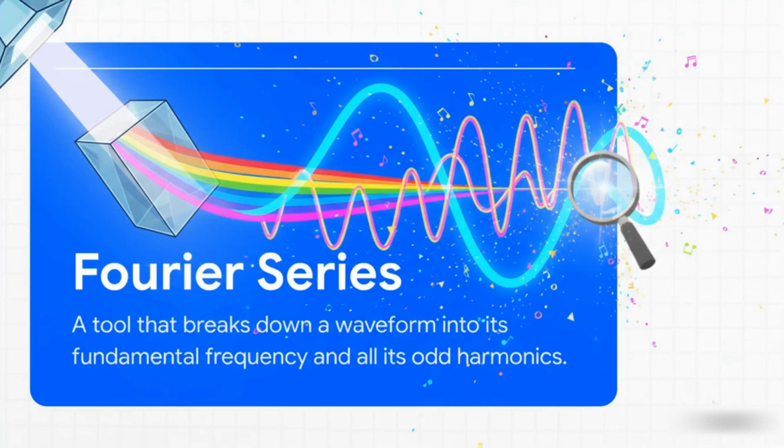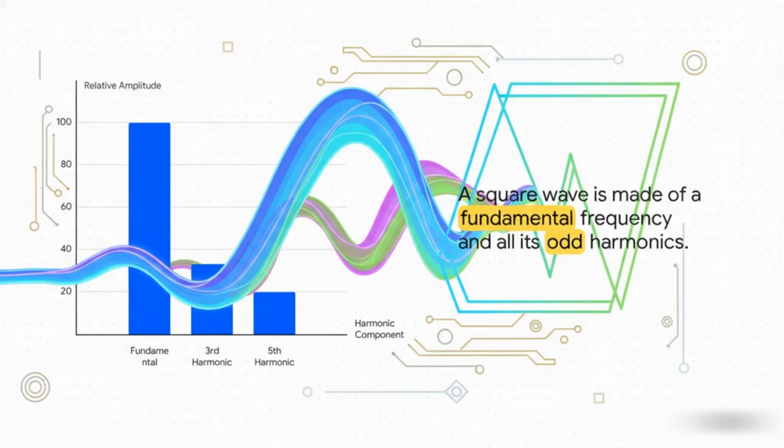You can think of it as a prism, but for electrical waves. Just like a glass prism can take a beam of white light and split it into all its component colors, red, green, blue, and so on, the Fourier series can take any repeating waveform, no matter how jagged or complex, and break it down into a simple recipe of pure individual sine waves. It shows us the main ingredient we want, the fundamental frequency, and all the extra stuff we don't, which are the harmonics.